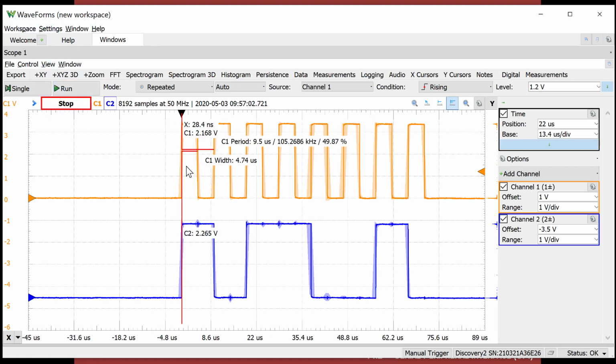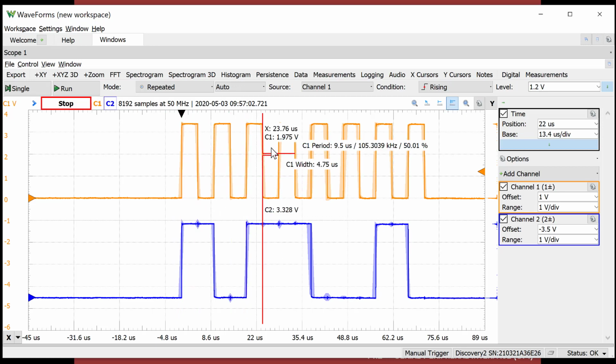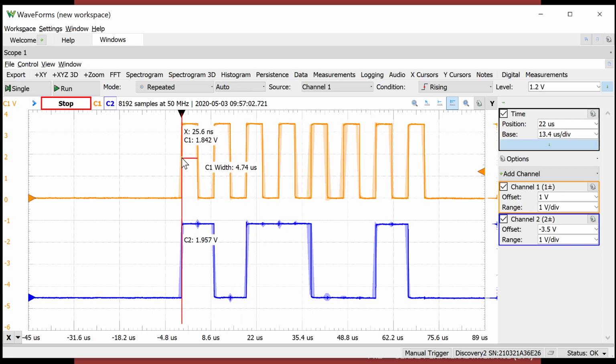A logic analyzer basically says, instead of giving you the analog voltage like an oscilloscope does, I'm just going to give you a 1 or a 0. So it has a threshold level, and if you're below this, you're a 0. If you're above this, it's a 1. That's cool because sometimes you only care about the logic values, and since the measurement is simpler, it can have more channels. The Analog Discovery, for example, has 16 logic analyzer channels on it.